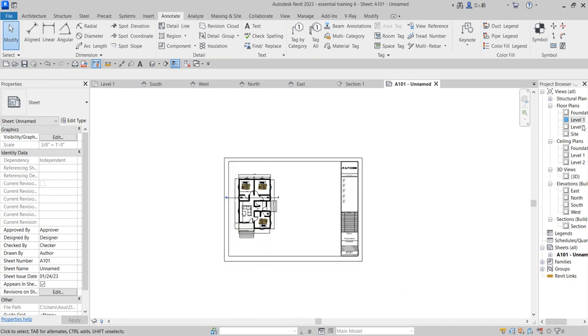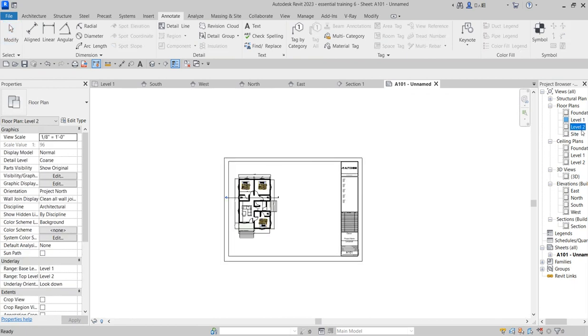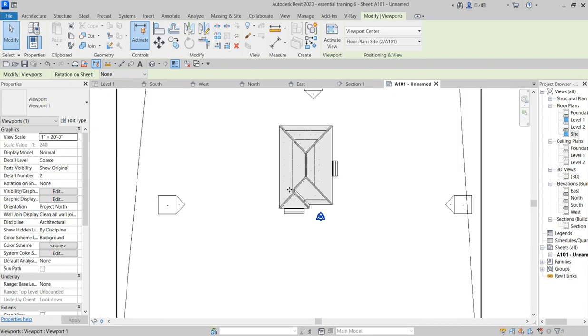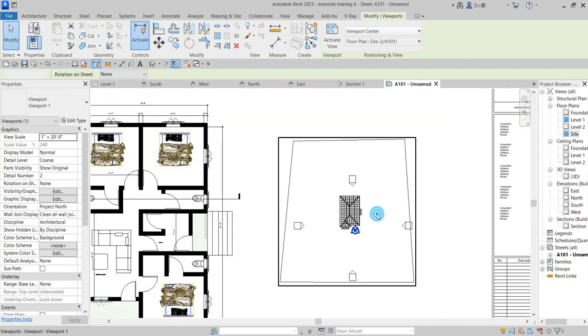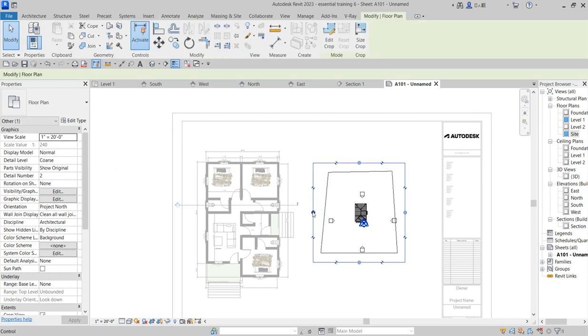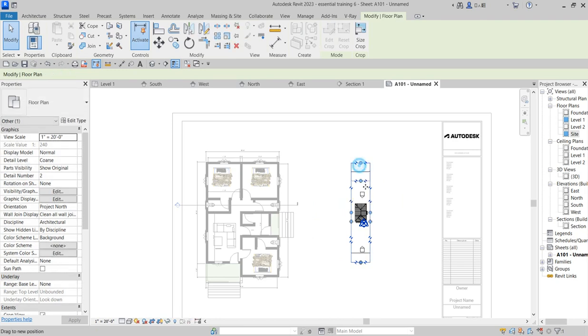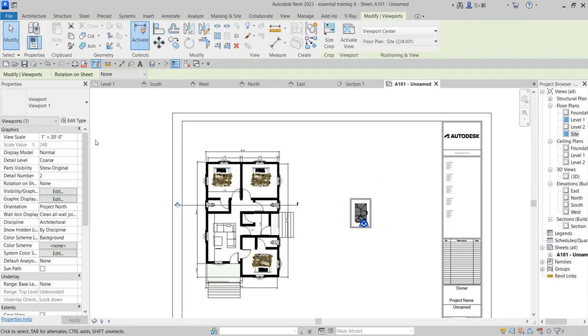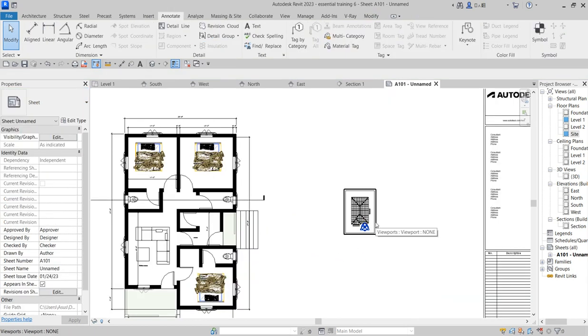Good. So you can bring another view, like say okay, the side one, you can bring it to this place as well. Are you getting it? This one will display the roof. When you select that, you select this and you set this to crop. When you scale, this crop is going to follow the scale as well. That's why I'm doing it on this smaller scale level. Here now you select this and you click this and you say none, so it will disappear.